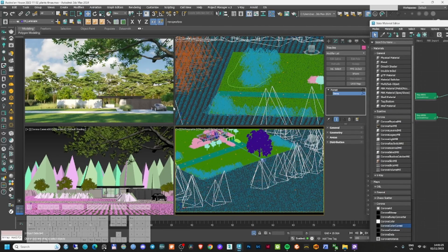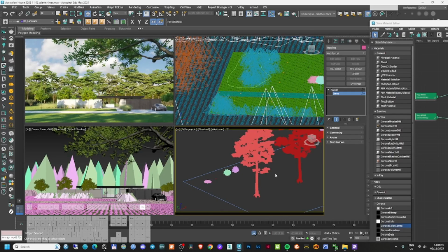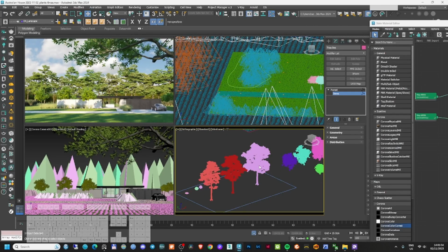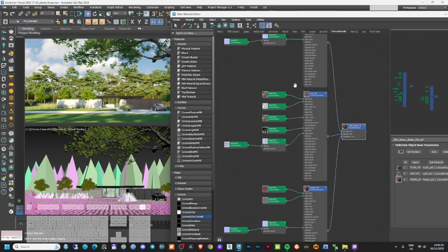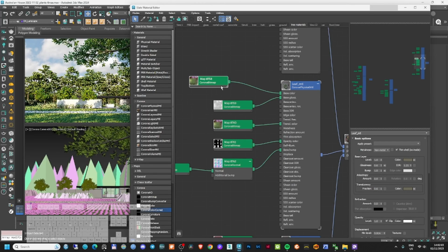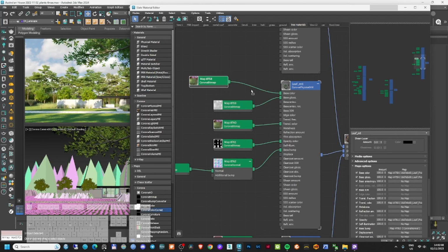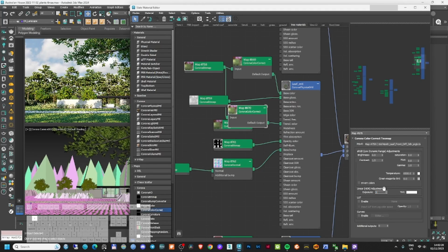Another thing are these bushes here in the back. I think I forgot to make a translucency also for those ones. Let me see where it is. It's this one. This material also, let me try to fix it. The leaf needs to be 0.6. This needs to be a little bit brighter. Color correct 5. Then with shift I'll make a copy, move this here and make this one. And the color of this needs to be a little bit more warm, so this should definitely help.